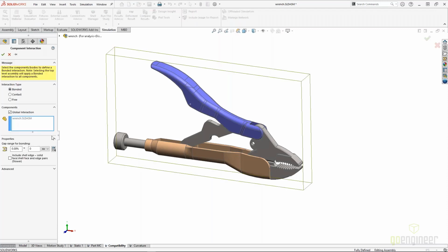In our global contact, we can specify whether or not these common nodes are enforced. Now, in 2021, 2022, 2023, it's called enforced common nodes. Before that, it's called compatible versus incompatible. Compatible and enforced common nodes is the same thing.